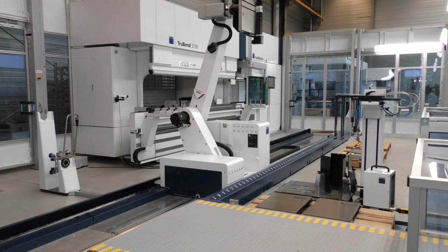On the mechanical gripper of the Bend Master, the part is already prepared. The Bend Master took the part from the sheet removal station. Also here we have installed a sensor to measure the thickness of the part. The first small plank is picked up by vacuum suction cups. Then the Bend Master uses the mechanical gripper to pick it up.